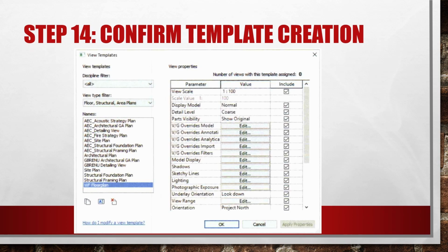Users can choose to create a view template that applies only a small but important adjustment, while leaving other settings flexible for specific situations, such as when using complex filter arrangements. Alternatively, a view template can be configured to modify nearly every aspect of the view, resulting in a highly controlled and precisely defined output. Select OK to accept all the defaults.